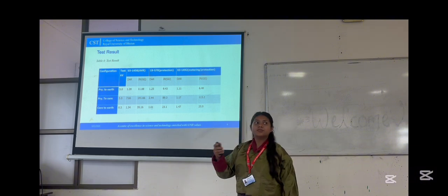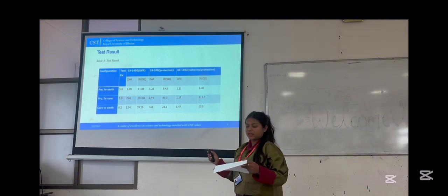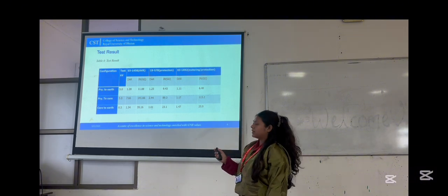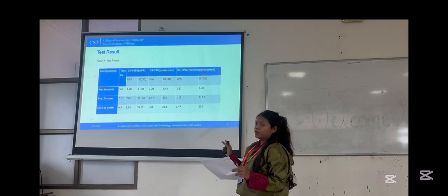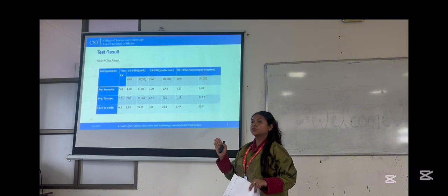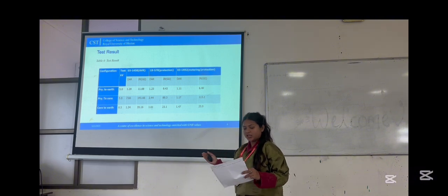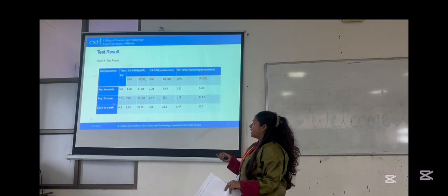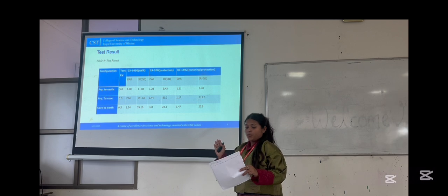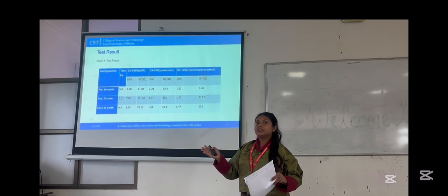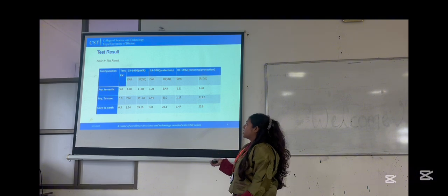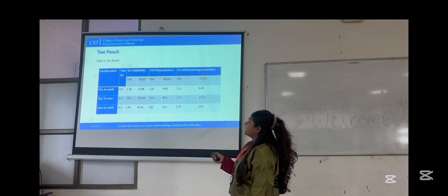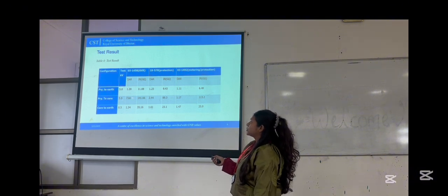In this test result, what we mean by the ratio is the ratio of resistance at 60 seconds to resistance at 30 seconds. We use this value, and when the ratio is higher than 1.25, it is good insulation, and here we can see that there is good insulation.